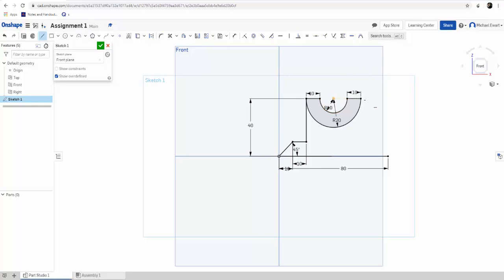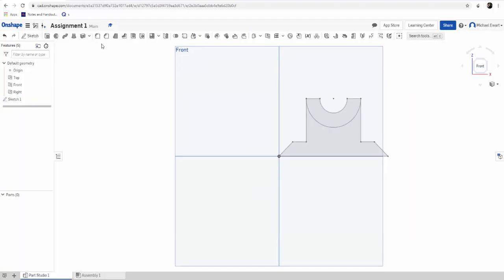Okay, now let's go ahead and continue this. We're going to go down. You should see this yellow line to make sure that they line up. And then we're going to go over by 10 and then down. So I'm going to add that dimension, and this was 10. And then I think it may already have defined that as 45. Yeah, so that's 45. We didn't need that one. That's why it's grayed out. If we want, we can get rid of it. So now everything's black, meaning it's all fully defined. And now we can hit this check mark up here to finish our sketch.